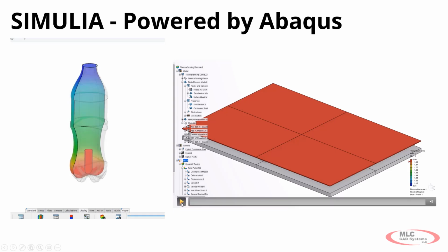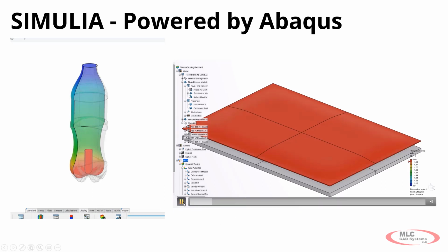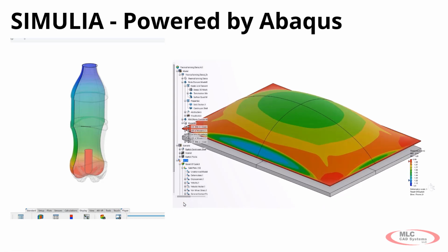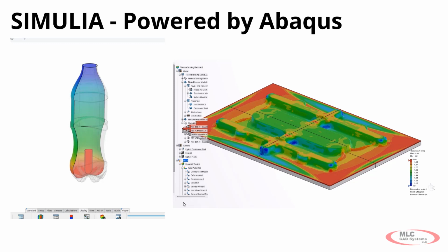Over here on the right, we have a similar but different process of thermoforming. You blow up this plastic with air, then you put your mold into it, and then you apply a vacuum to suck down your shape. You could be answering the question, is this going to break as I do this mold process? These molds are very expensive to make, so you could save a lot of money by simulating this beforehand, before having to make another big mold like this. But those are some examples. Parts with high deformation that are interacting is where you go to these higher level products.